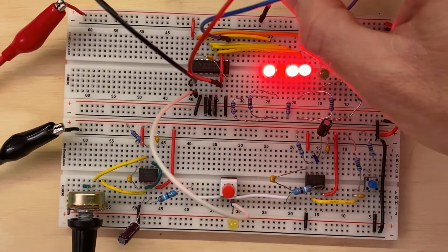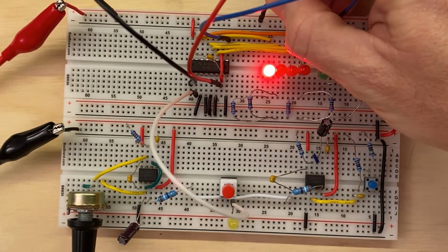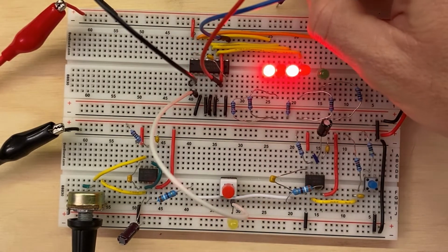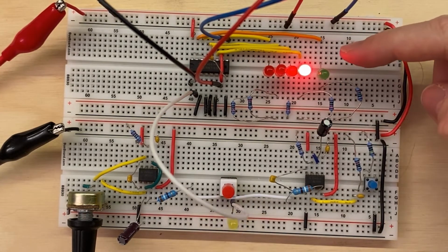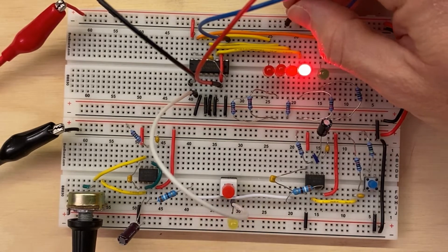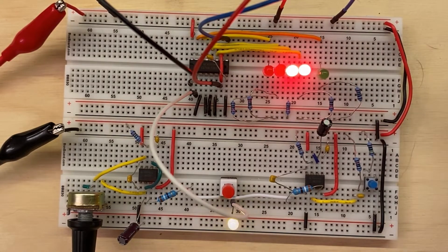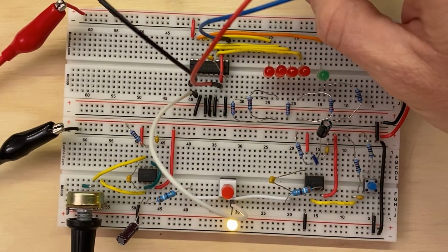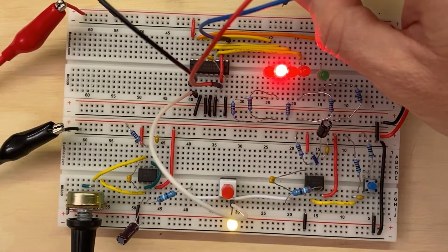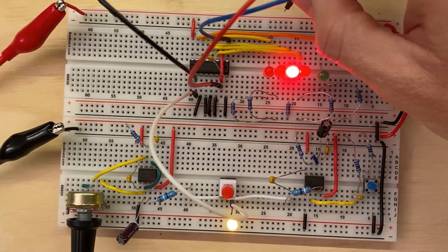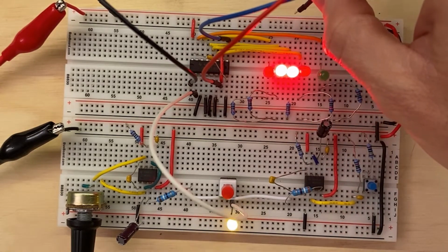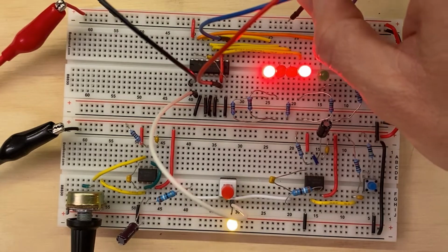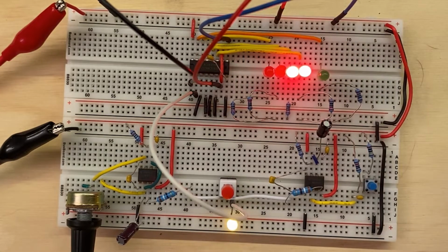And of course, here's our enable pin. So if I pull this out, wait till I get to a number, and I put it to ground, of course, then it's just going to sit at whatever number I've set it to. And if I go back high, well, it's going to count again. You notice it also keeps counting. Oh, see now, there it does. But you see it's erratic. That's why you always want to have your inputs either low or high, because you just can't trust them to do something. You want it to count, you put it on the 5 volts.